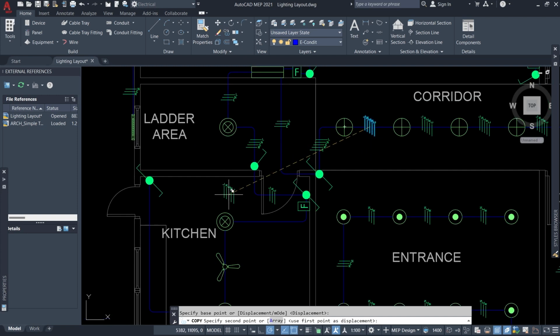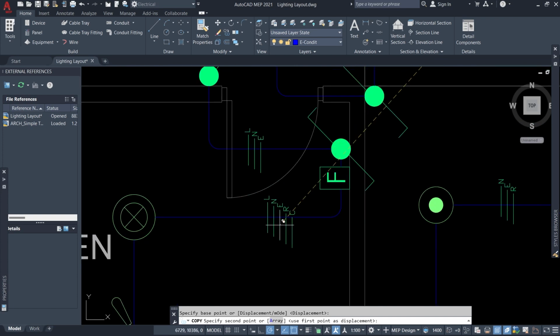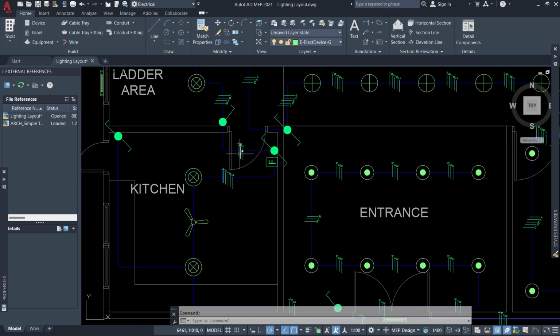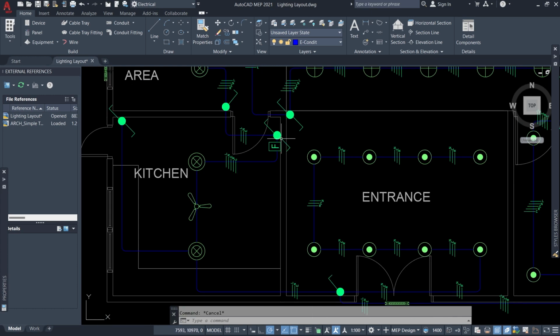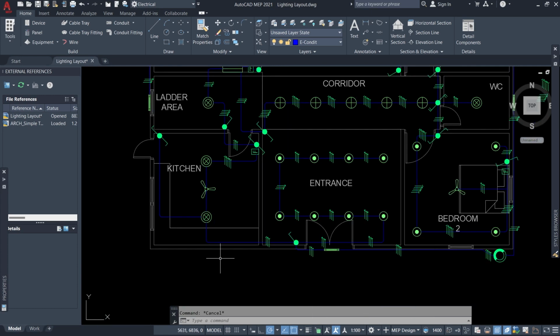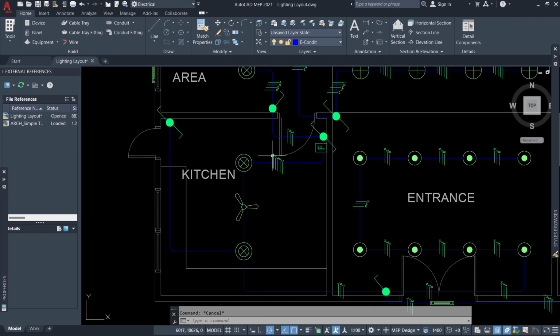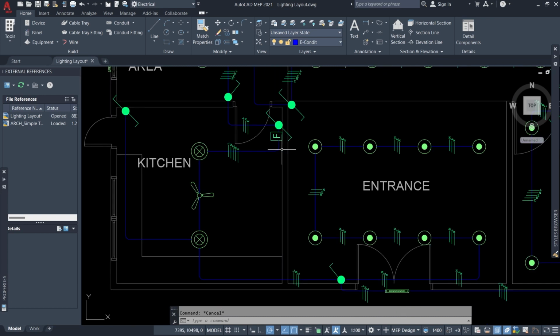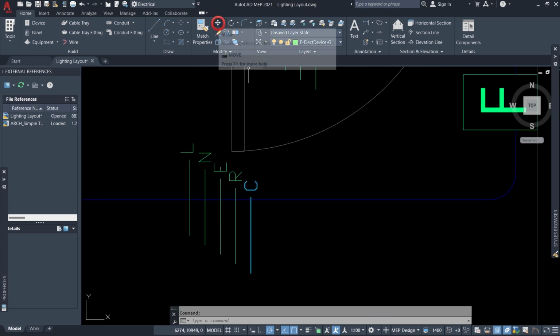Let's go through that. Remember, the live is coming from this place, and once it enters here, we are not taking any live line out again. But we are, because there's a live cable running from this switch to this part of the circuit. So we're going to hold on to the live cable, and here the return will have to be 2. Okay, the return will have to be 2.